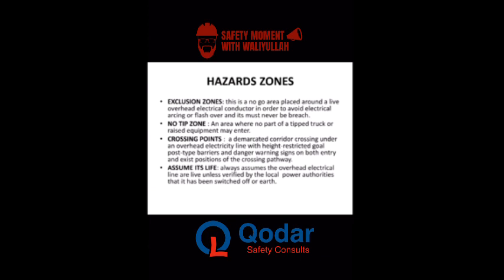If you go to some construction sites where their generator is or some high power equipment, you always see a no-go area. I'm sure we must have seen it on our construction sites. Well, that no-go area is what we call the exclusion zone. This is a no-go area placed along an overhead electrical line to avoid arcing or any contacts. That is why it is clearly defined as an exclusion zone and a no-go area.